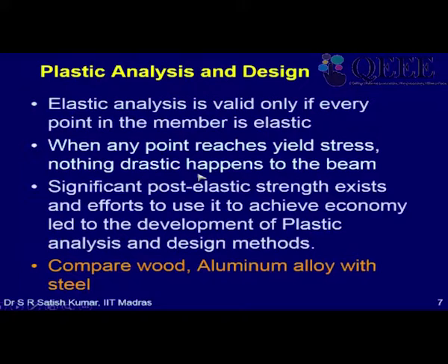Okay, so that is one part, but apart from that, it was realized that when you go on increasing the bending moment or the load, until some point in the beam reaches a stress Fy, the elastic analysis is not valid beyond that point, but then nothing drastic happens to the beam.